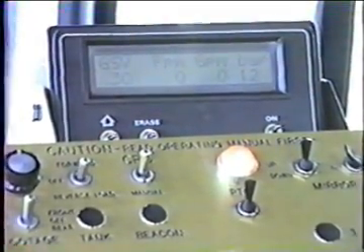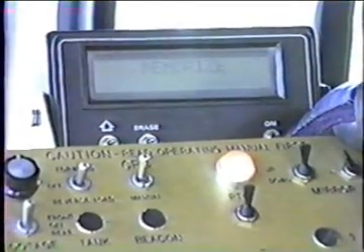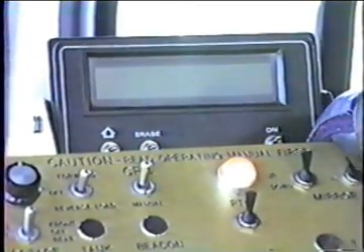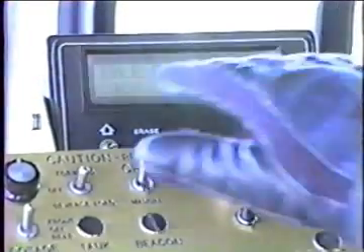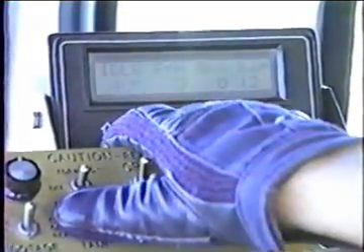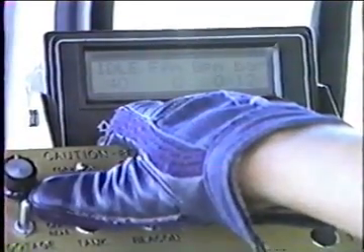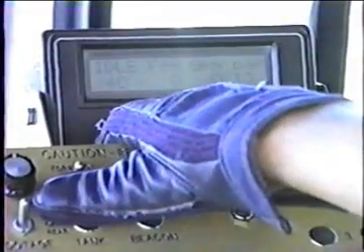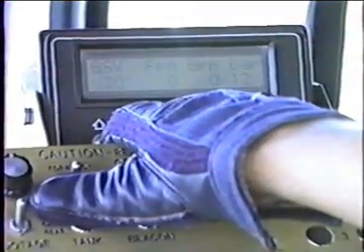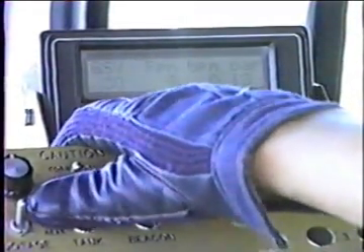Turn it on, set the idle at whatever you want, and if we've decided 40 is what we want, this comes on at 40 every time. We don't have to fool with that. Put that into the GSY position, set the spread rate. Let's say today we want to shoot 4/10 of a gallon. Hold that up to where we read 4.